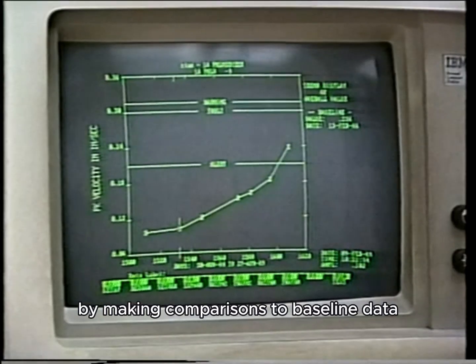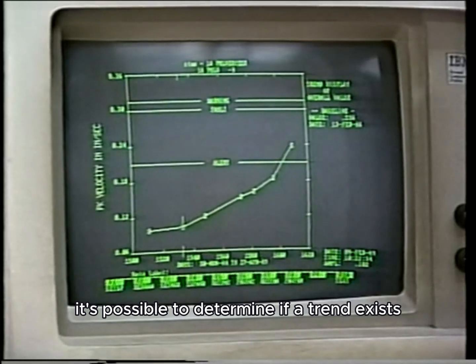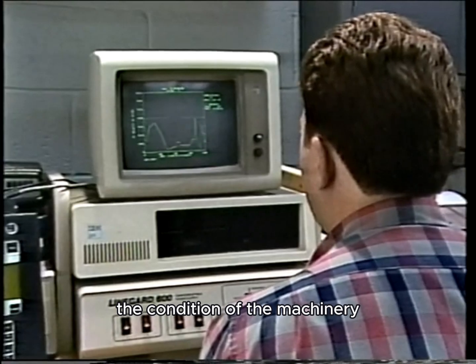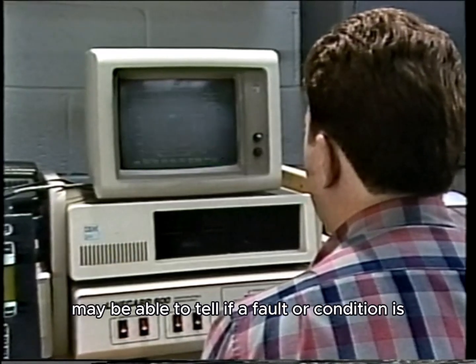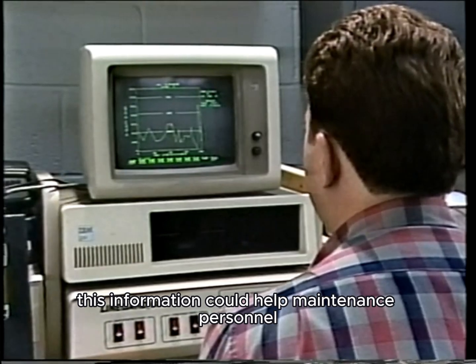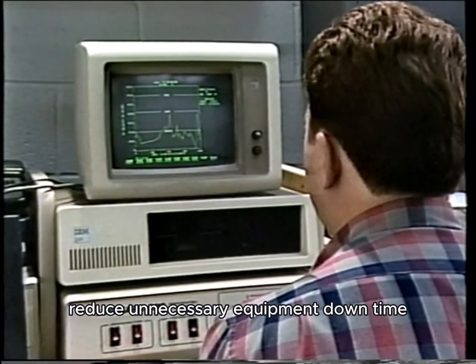By making comparisons to baseline data, it's possible to determine if a trend exists. In other words, the person responsible for monitoring the condition of the machinery may be able to tell if a fault or condition is getting worse. This information could help maintenance personnel reduce unnecessary equipment downtime.